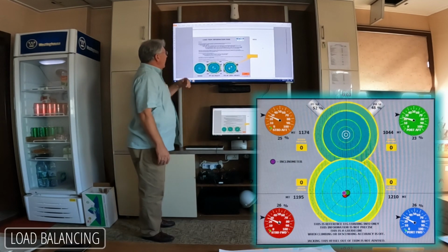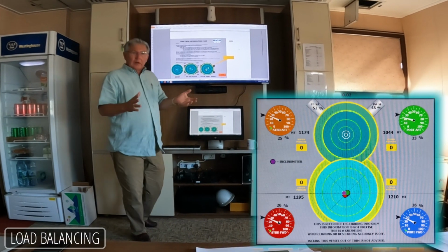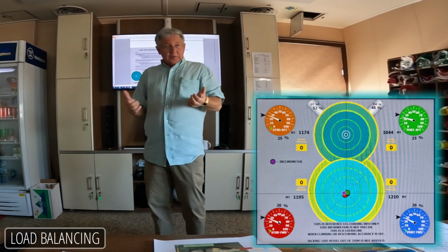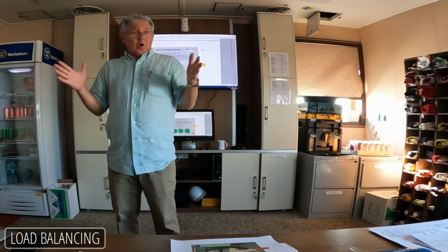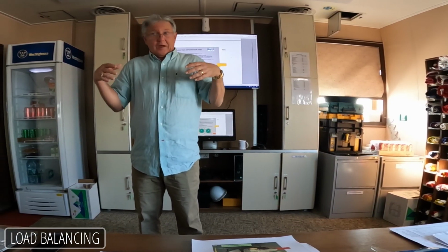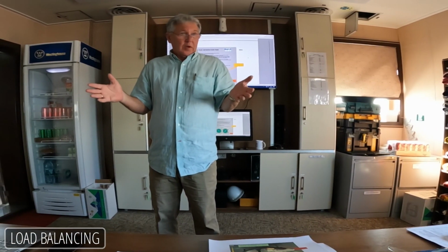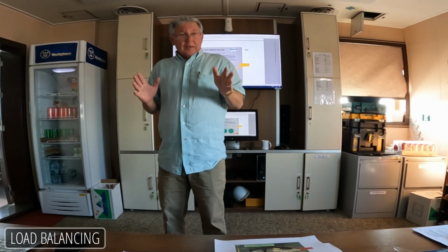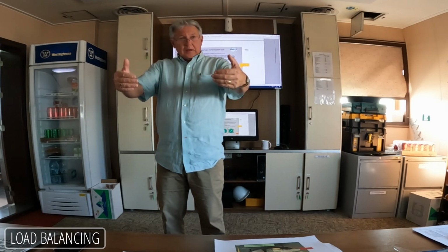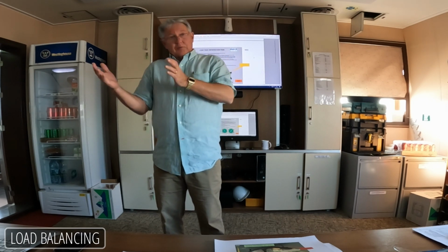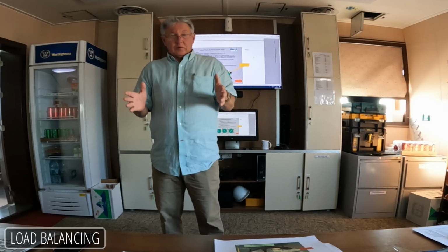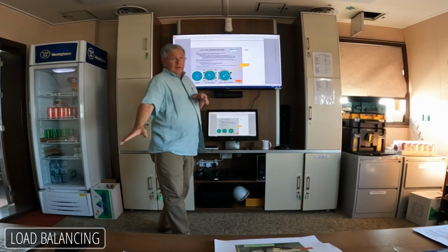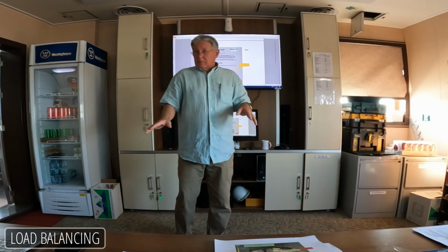So this page is designed to aid the operator in graphically looking at the loading of the leg. See, when you jack a 4-legged boat, it's never going to self-level itself like a 3-legged boat. Either one leg's heavy, or the front's heavy. But the biggie: if the front's heavier than the back, it's not the end of the world. If the port's heavier than the starboard, it's not the end of the world. So long as it's balanced diagonally, then you're not going to have the table rocking.